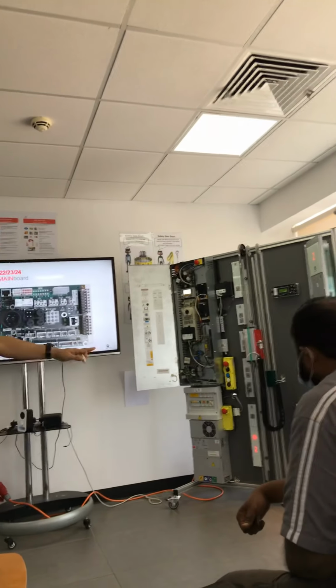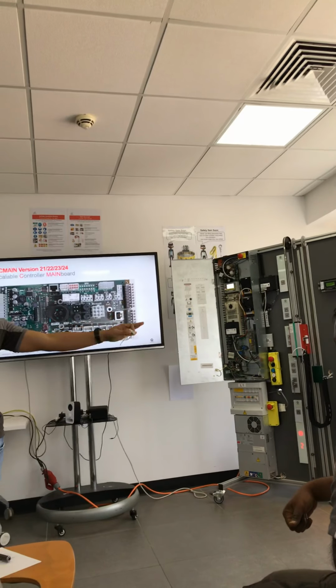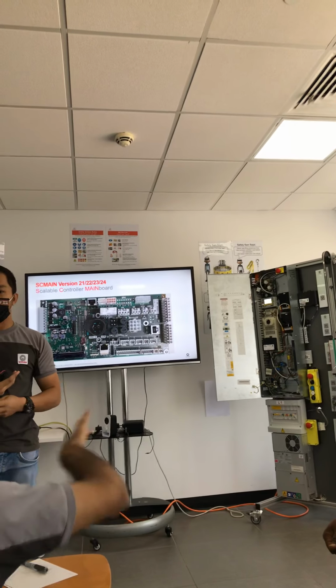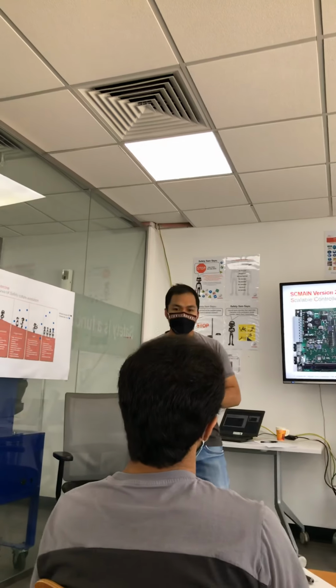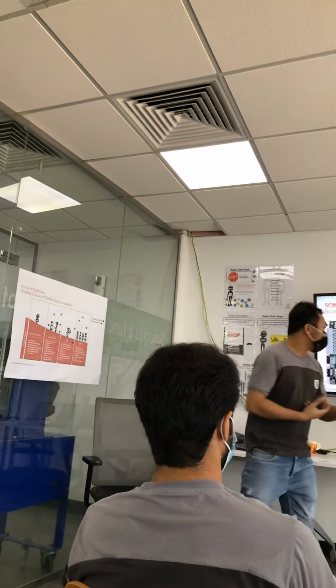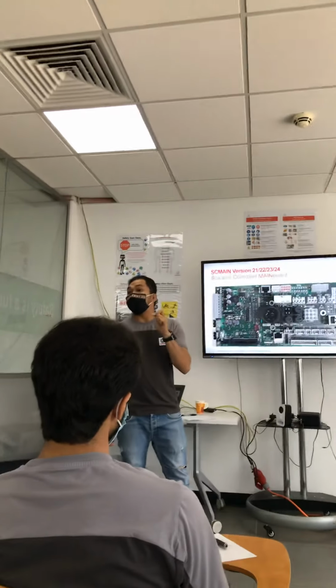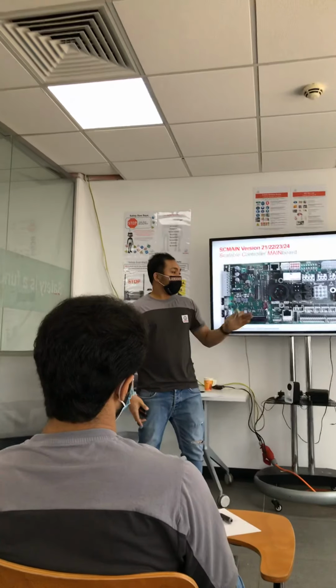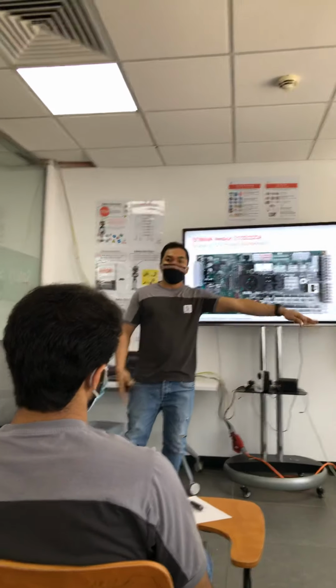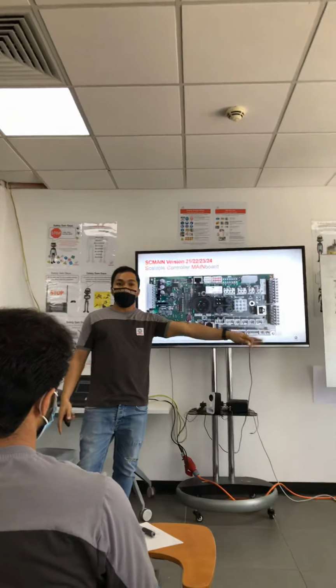Because maybe you have some problems with the PCBs or COPs or with the car doors. We need to isolate. Yes, this is the right word, isolate all the car. That's why during operation of new installations, they are using this one, because normally when they are doing it, they can run the elevator without the PCBs on the top of the car. So during normal operation, this is empty.